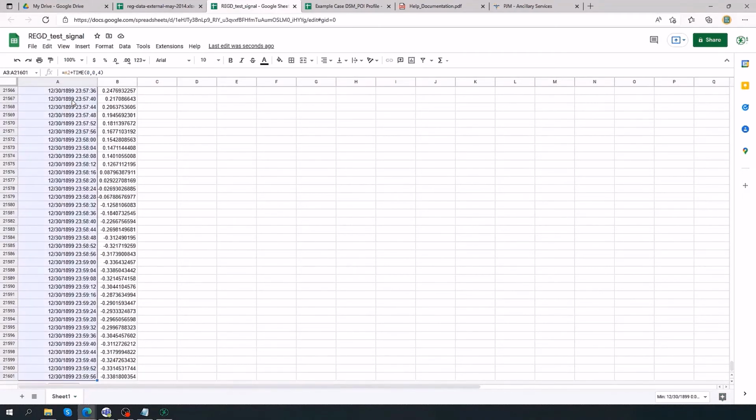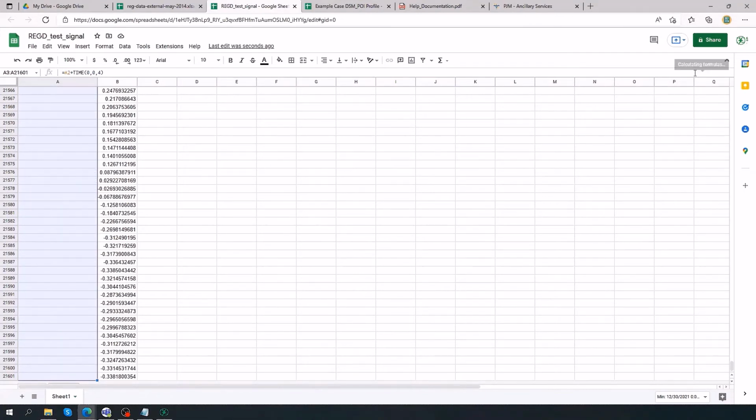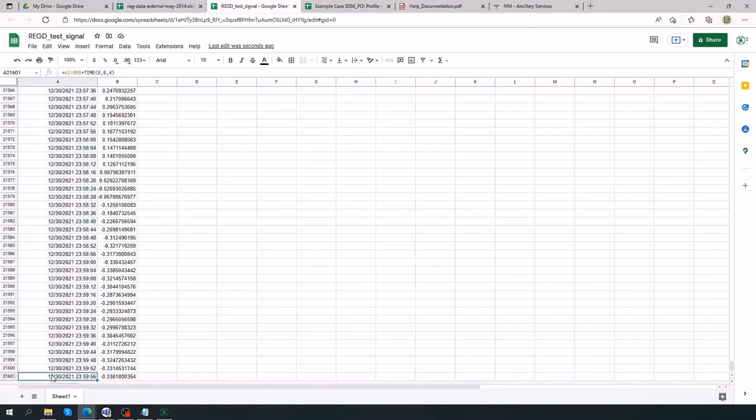Select the entire first column and hit Shift-Control-D, which applies the formula to the entire column. Once completed, we can see that we now have 24-hour time series data in the format that is required by Storlytics in 4-second resolution.